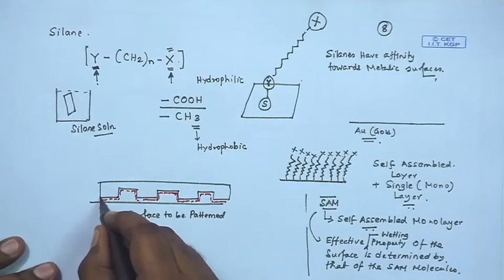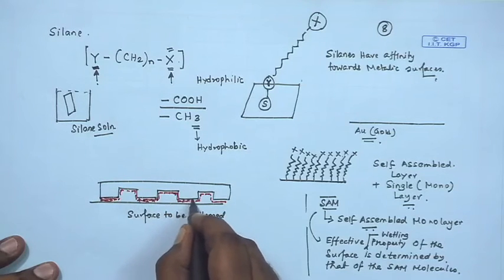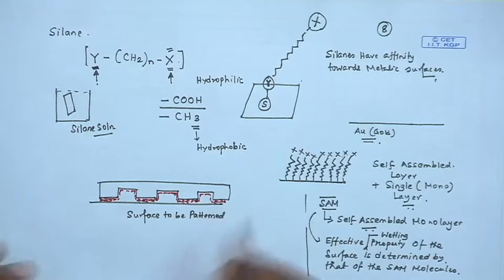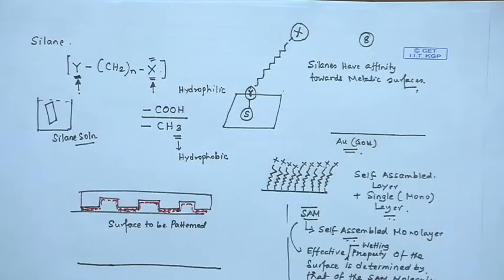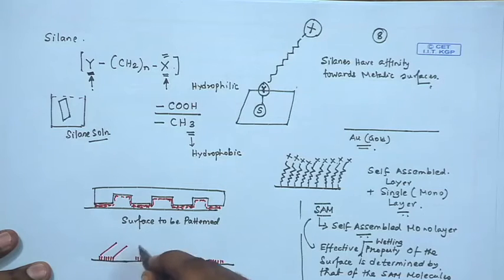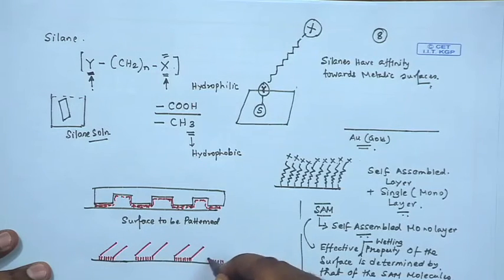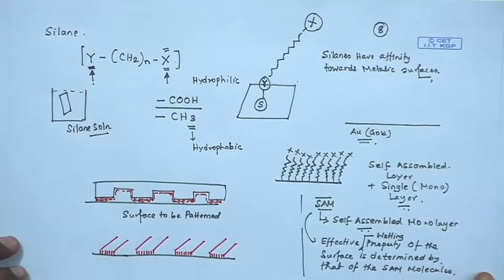Right, and so when they are in contact, in fact these areas, the liquid is in direct contact with the substrate. So, ideally the silane molecules present over these areas should get an opportunity to bind to the surface, while other areas it will not bind, and therefore you end up getting patches with alternating wettability regimes.